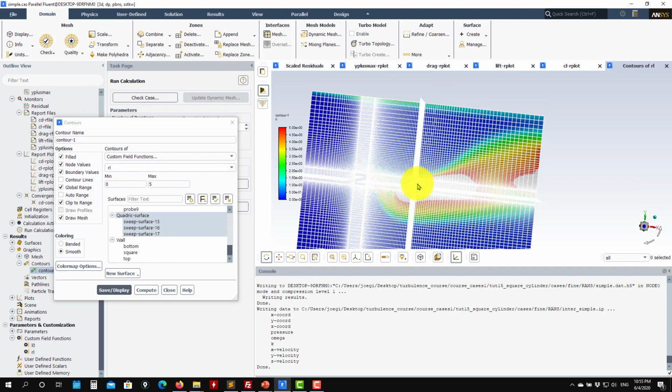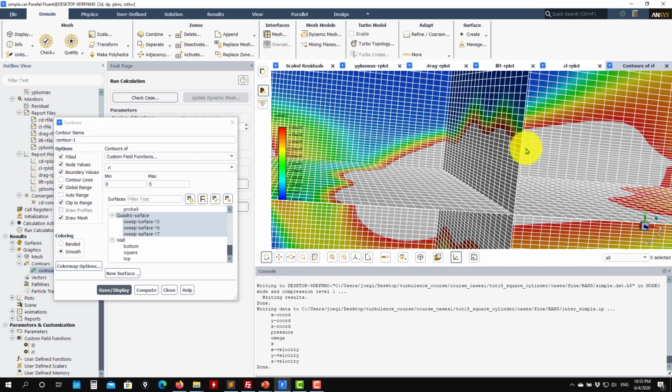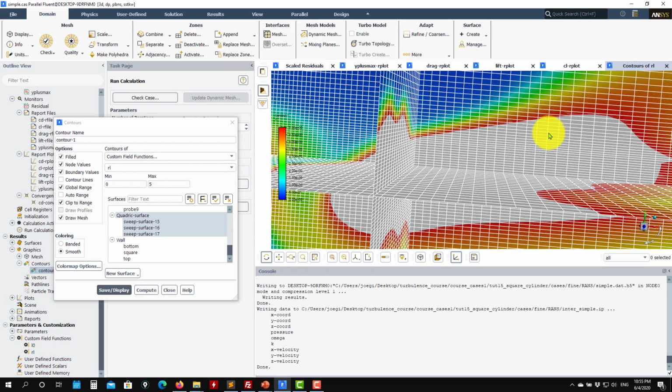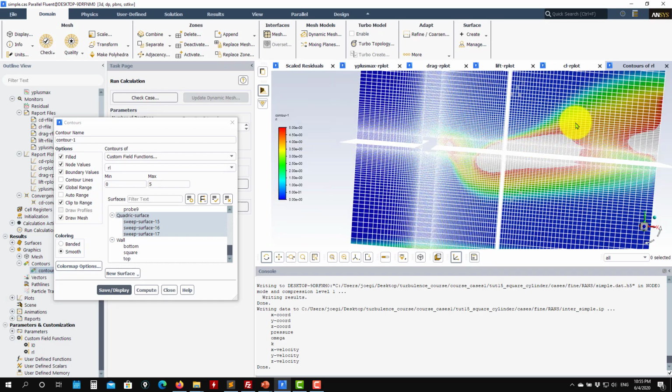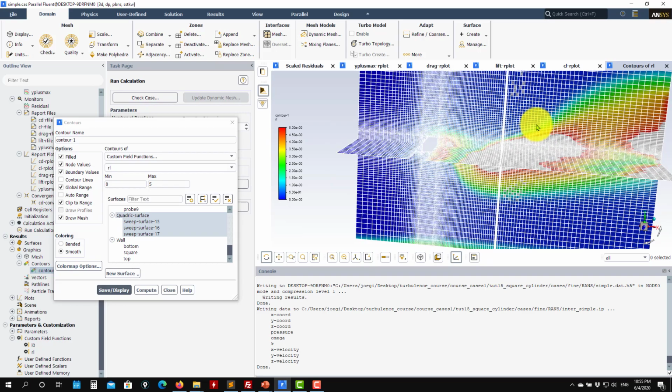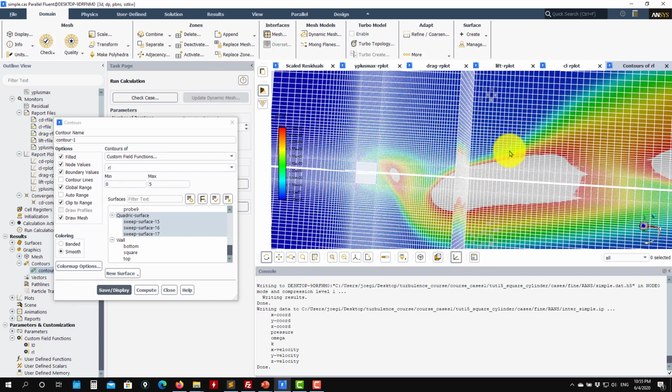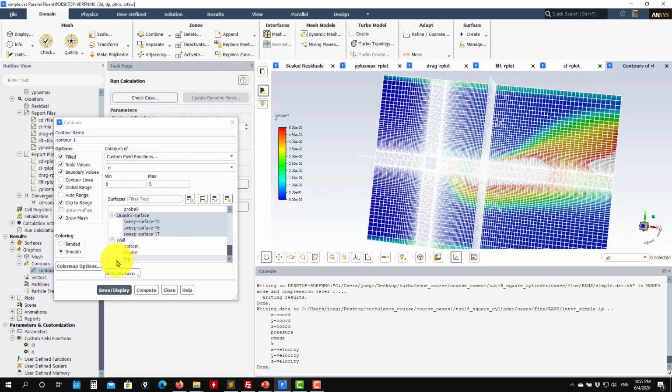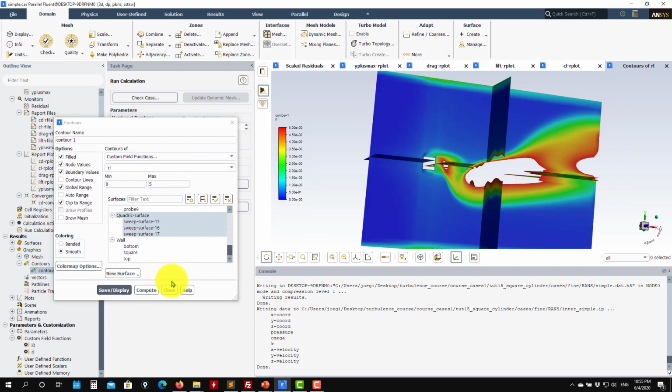So starting from this mesh, you can start to do some refinements. See here that maybe it would be better to make another refinement in the X direction. The Y seems to be okay. So you see that this criterion is giving you a lot of information.